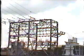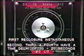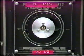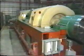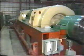For distribution feeders, the breaker in the substation is often fitted with a reclosing relay. The first reclosure may be instantaneous, but the second, third, and fourth will each have a time delay of 10 to 20 seconds. In setting the reclosing relay, it's necessary to know the types of load which are supplied by the particular feeder. For example, the feeder may supply an industrial load which includes large induction motors. Reclosure must be delayed until the motors have time to run down and reduce their residual voltage to less than 1/3 of rated.